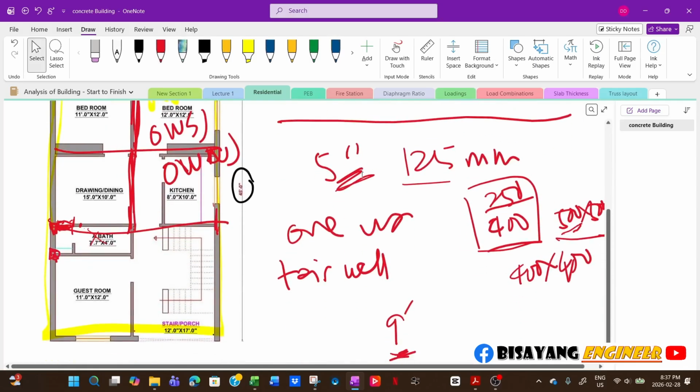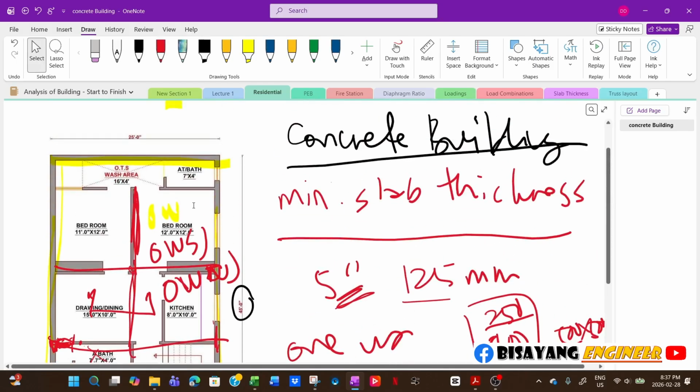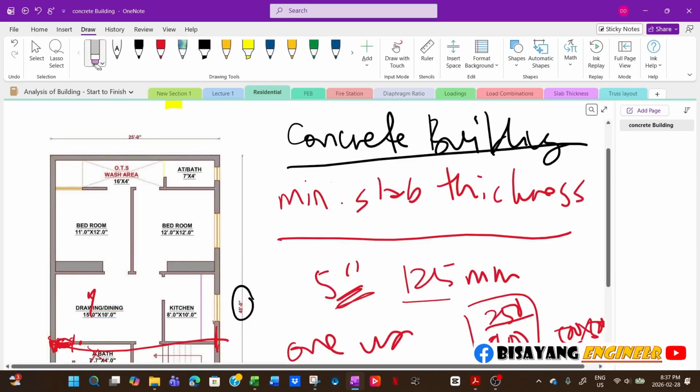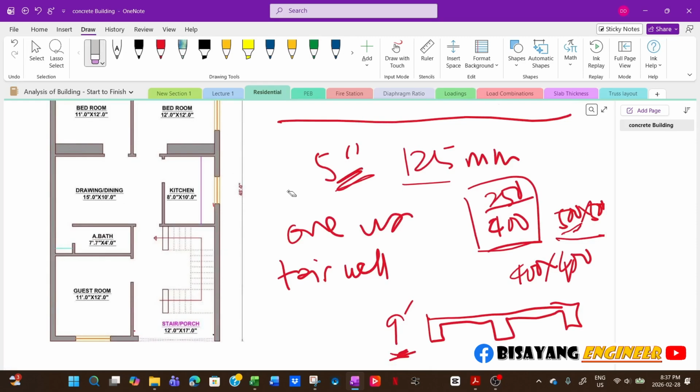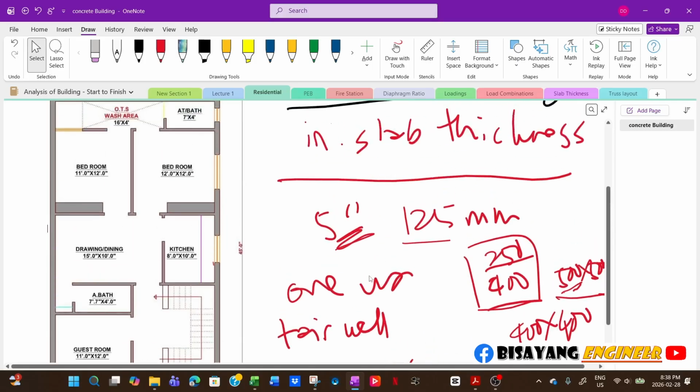If you cut a section here, that section, then you have your slab here, then the perimeter beam, and then another beam here, like that one. Now, if the architect doesn't like a beam in this direction, then you will be forced to span. At the end of the day, whether you like it or not, it will be the architect who will dictate the framing layout, and then our job as structural engineers is to make sure that whatever the architect wants, it will work.